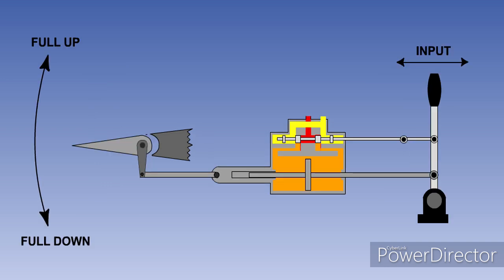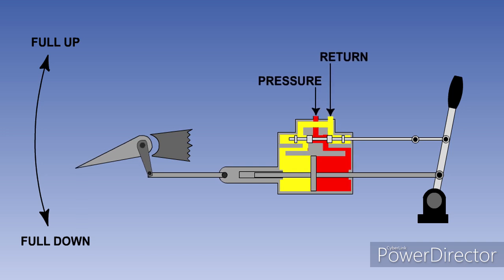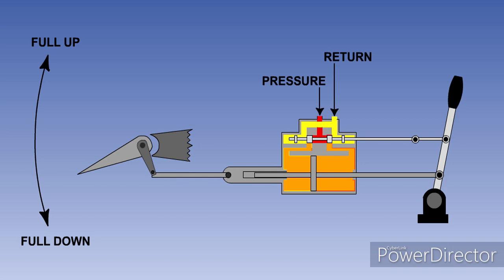We will now look at the operation of the system with hydraulic power available. Once again, when the pilot operates his control, the hydraulic lock will cause the actuator body to move, and with it the flying control. Because of the position of its connection on the control column, the servo valve will move further than the jack body. So one port of the actuator will open to hydraulic pressure, and the other will be open to return. The hydraulic pressure will attempt to move the actuator ram. This movement will be opposed by the pilot, so instead the body will move in the opposite direction, moving the flying control.